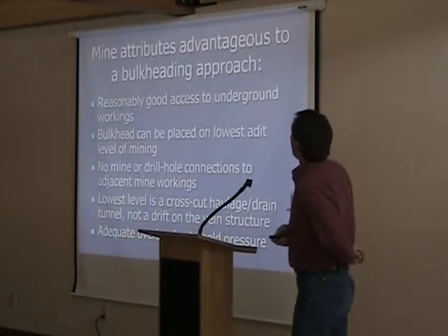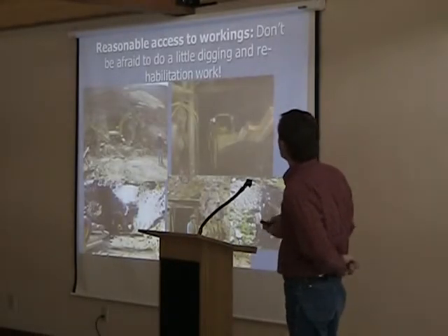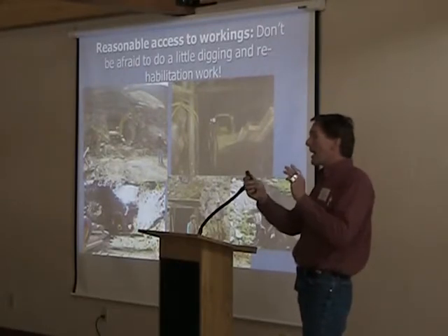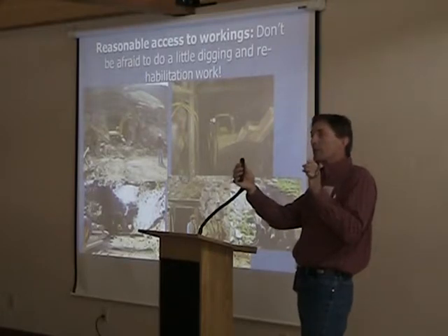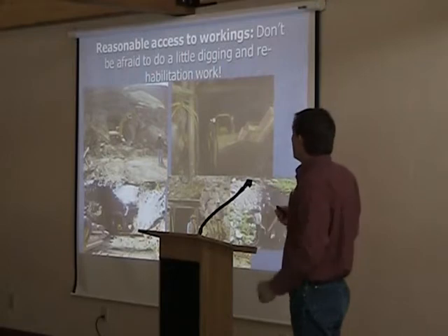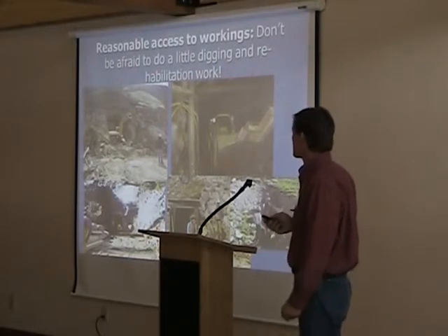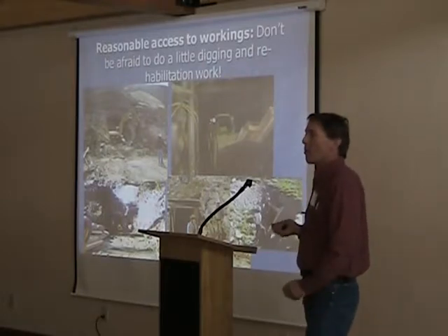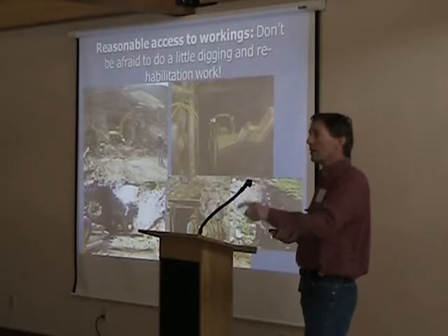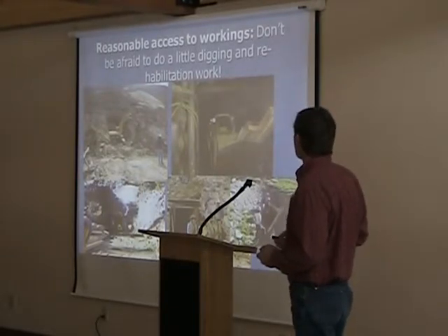So what we want to do is not give up too quick. If we see that we have a nice crosscut tunnel, we might have a mine map that showed that the first part of the tunnel was timbered, but then it's an open rock crosscut. Just because that's caved at surface, we don't want to give up too soon. And we've had some pretty good successes in getting back through portal blockages and rehabilitating portals, and then we're getting into some really good underground workings, and we don't have too many issues with rehabilitation work.